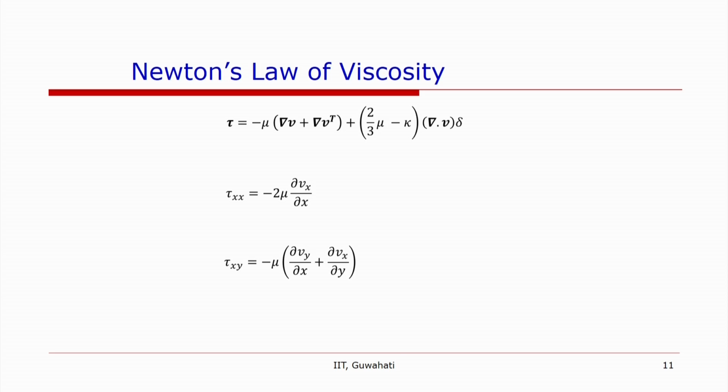So, Newton's law of viscosity relates tau and shear rate, which is sometimes represented as gamma dot, or one can say that for one dimensional flow, del V over del Y. So, if over a surface there is a flow, then the shear stress tau can be written as minus mu del V x over del y, where this is the x direction and this is the y direction.